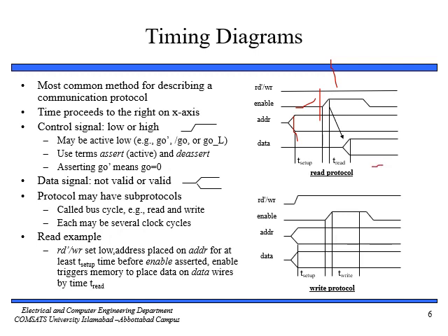So this is the time. In this time, we must place data on the data wire. There are two times that we need to consider. When the enable signal is high, we need to have had the address on the address bus at least t setup time before, and once the enable signal is high, we need to put data on the data bus after t read time. So there are two times here: one is t read, another is t setup.